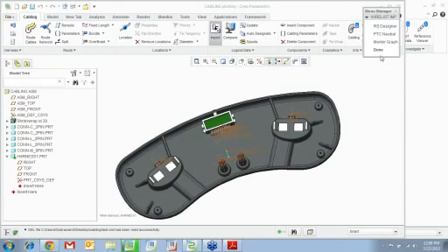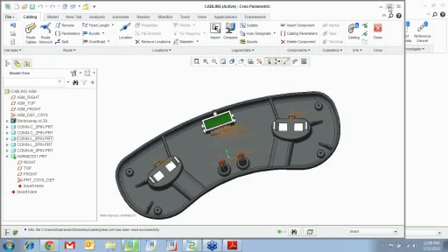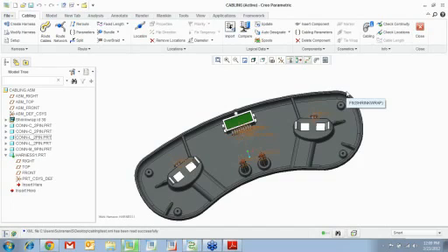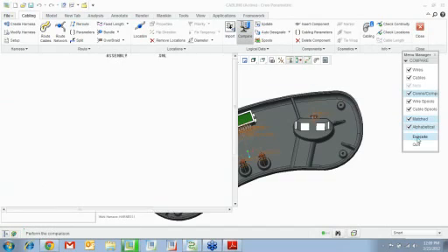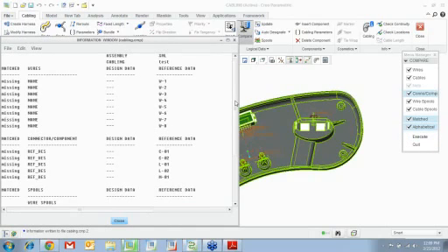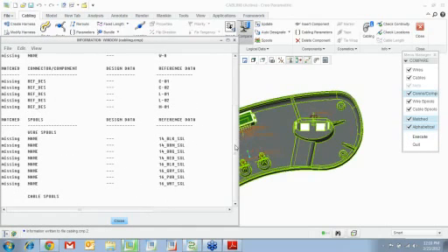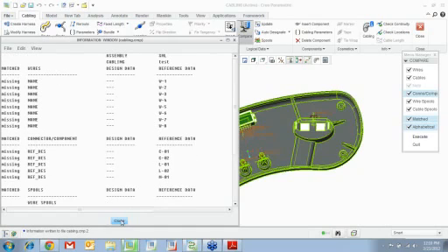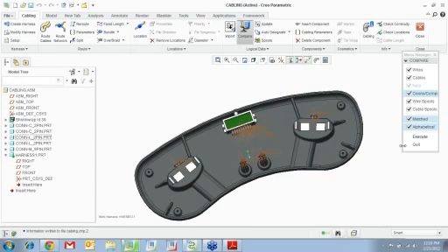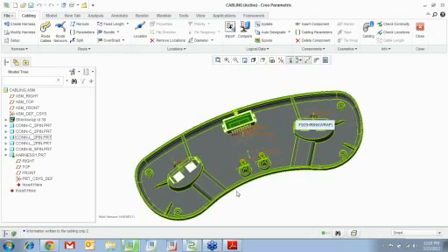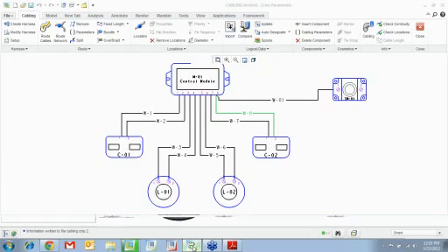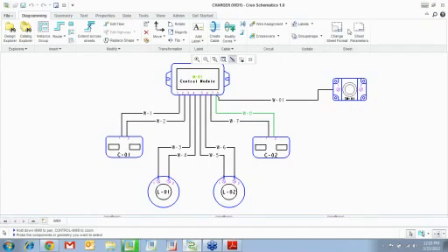Say done and done. Now once you do this, you have some tools which enable you to compare what you have in your ProE assembly and what you have in your XML file. So when you go compare it, you can see the XML file has tools and the design does not have it. This is your assembly. Okay. Now, the next thing we're going to do right here is to designate. I want to designate this component to be the same as this component, right? So you have to designate it.